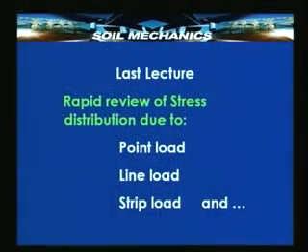In the lecture that we had just prior to this, we discussed the three different types of loads that we apply, normally through a foundation, onto the soils. The three types of loads are, as you know very well, point load, line load, strip load. You may also add, if you like, uniformly distributed load. This is actually nothing but a strip load, but acting on a rectangular area of finite dimensions rather than an area of very long length and short cross section.